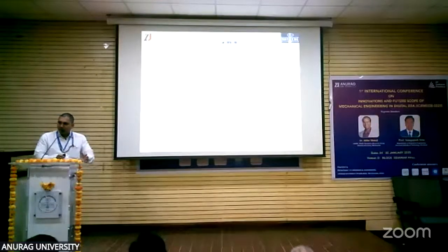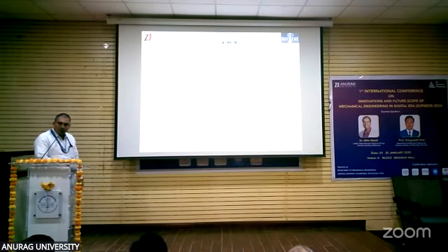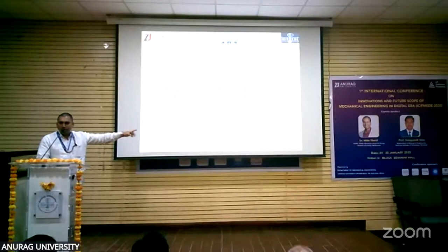Why these particular maximum and minimum values? Climatic parameters play a key role here. On April 12th, 2023, we had very little cloud, only 1% cloud cover, and the temperature reached 34 degrees Celsius. But on December 4th, it was 100% cloud, the whole day was cloudy, the humidity reached 94%, and the temperature was very low, 23.4 degrees Celsius. That's why we got a very low power value from the plant.